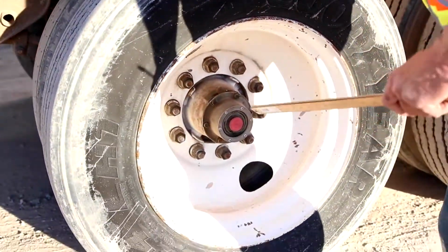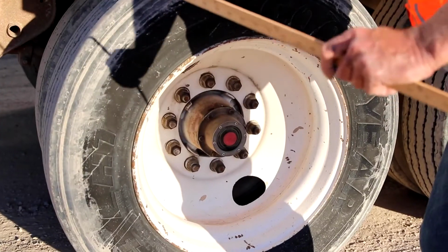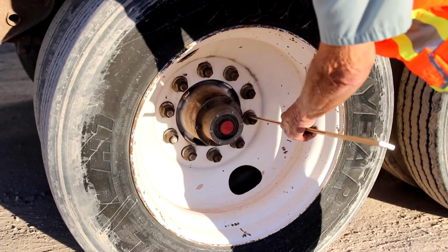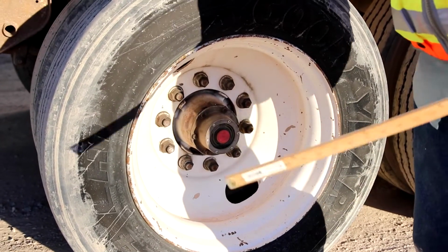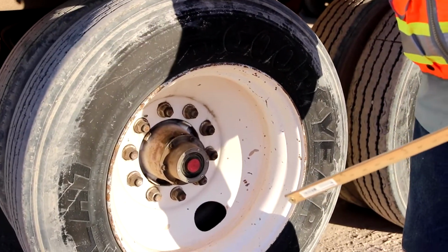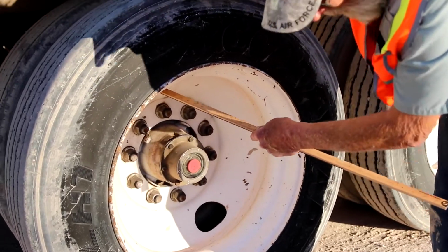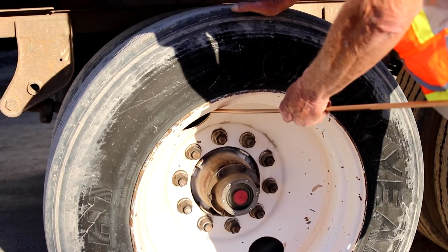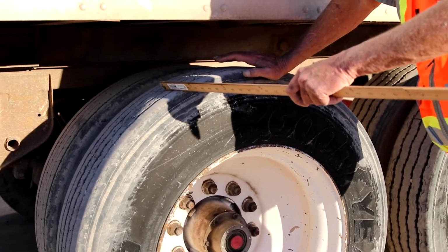Coming to the outside, my outside rim is not damaged or broken. No illegal welds. Lug nuts are all present, not missing. No rust to indicate looseness. No silvering to indicate over-torqued. My valve stem and cap mounted securely to the vehicle. No audible leaks. At least 100 pounds of air pressure per tire, minimum.